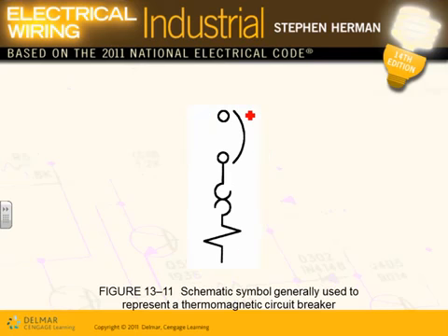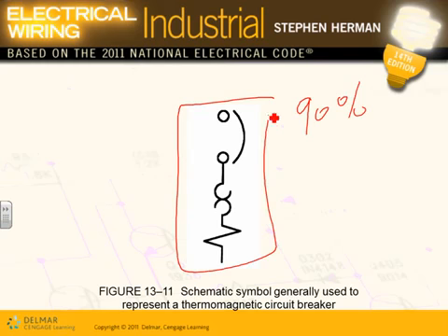they use, a different application. Now, 90% of the time, guys, your circuit breaker will have a dual component. This is called the thermal and magnetic, thermomagnetic circuit breaker. Can I have thumbs up? We know why thermomagnetic. It has a coil that trips on short circuit and a resistor that heats bimetallic material.